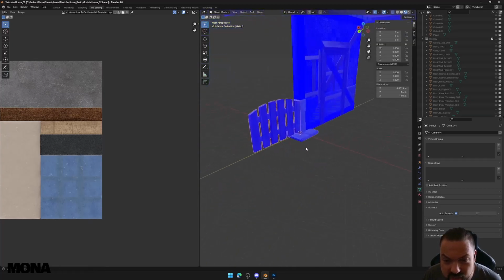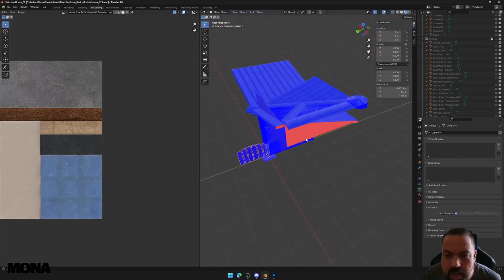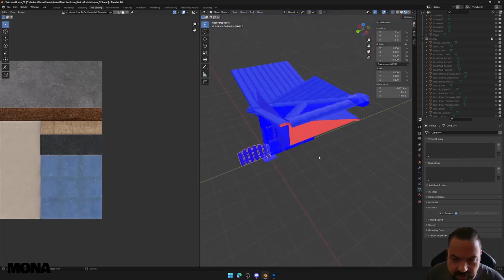No, it's not that. That said, while we're here, face orientation is very important because in game assets, you only have one side of the asset, right? There are ways to do it, and we'll look at that in a second with the material, but that is more expensive, or a little bit more expensive. So unless it's very important, it's generally recommended not to use double-sided assets.